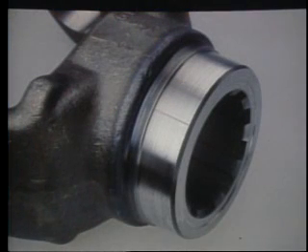In order to achieve the required surface finish, the yoke seal surface must be plunge ground. But even when the correct equipment is used, microscopic grinding marks are formed. These random grinding marks, which are so small they cannot be seen by the naked eye, must be perpendicular to the center line of the yoke splines to prevent leakage. Yoke manufacturers have made efforts to control this surface condition to eliminate low mileage leakage or accelerated seal wear.